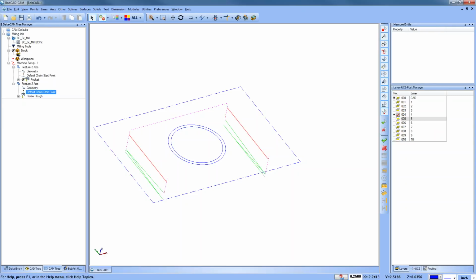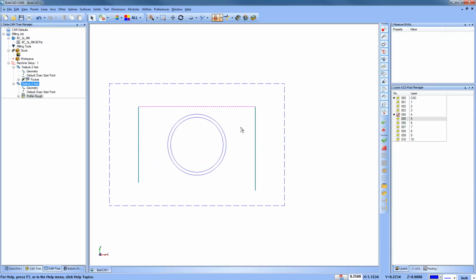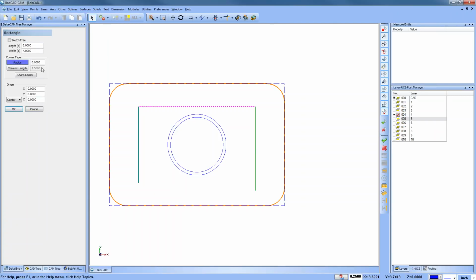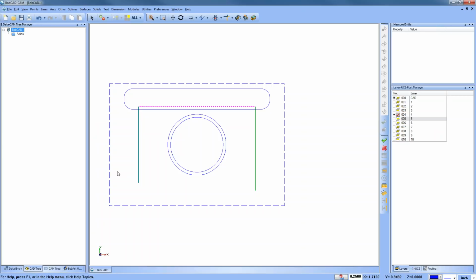Okay, so we're on a profile here. We're doing contour ramping, so the tool's moving back and forth. That is a great tool to use for slots. Here I have just centerline slots that I'm using. Let's say it's a 5 by, you might have a slot like this that you want to machine.